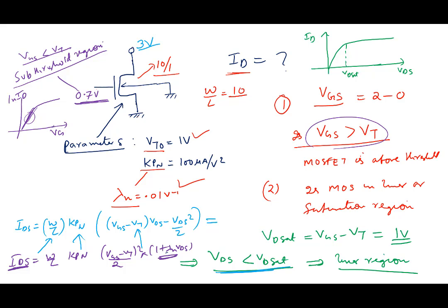So you may sometimes operate a MOSFET below VT, where the MOSFET current ID is proportional to e to the power qVG by eta kT. The relationship starts to resemble a bipolar: current is exponentially proportional to the base voltage. In this case, current goes exponentially with gate to source voltage. This is how you end up calculating the characteristics of your MOSFET in the saturation region.